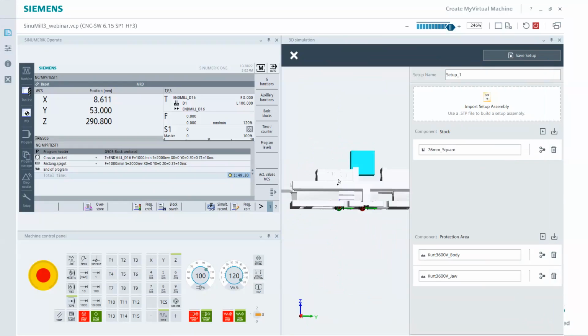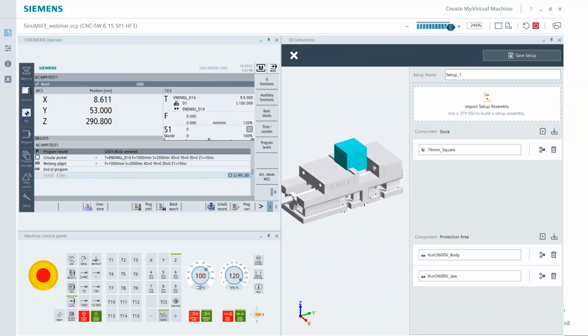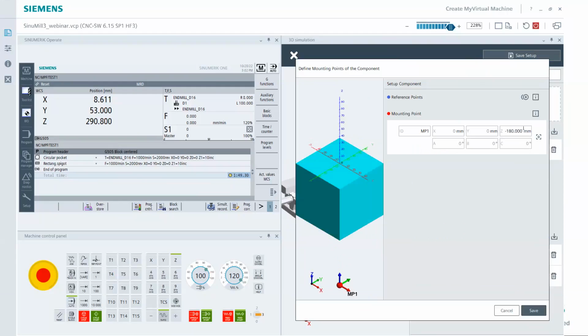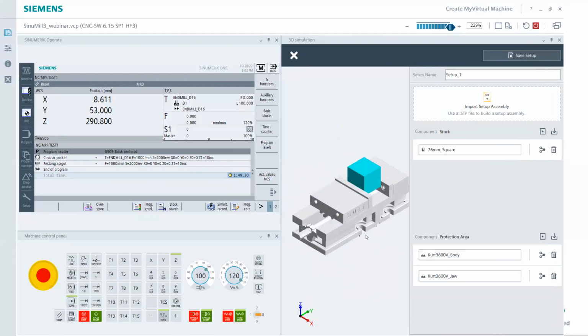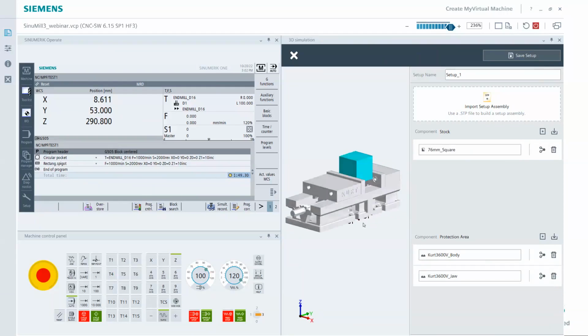Certainly, if I knew the exact dimension from the top of that jaw to the bottom of that vise, and I knew the exact dimension of this block, it makes it kind of super easy. I can just plug in the numbers, do a little simple math. But I'm just using this little offset to type in the value. I want to shift it, and the direction is going to be plus or minus, and eventually I get it kind of stuck where I want.